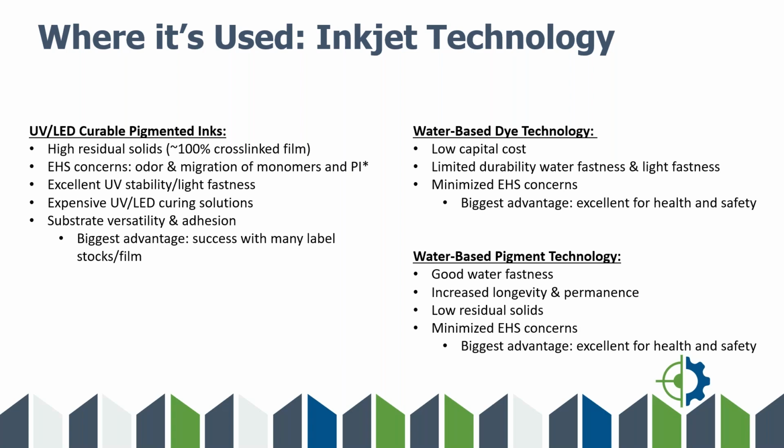And you have high residual solids in that ink. So everything you jet down to the page gets cured and anchored to the surface. So it allows you to do a lot of unique hybrid printing applications as well. It's great outdoors, great UV protection, great water fastness and durability as well. So anyone in the durable label space, this tends to be a really strong technology for that.